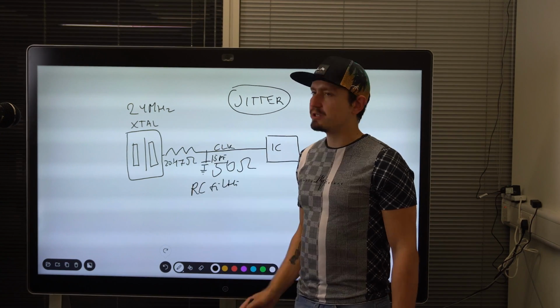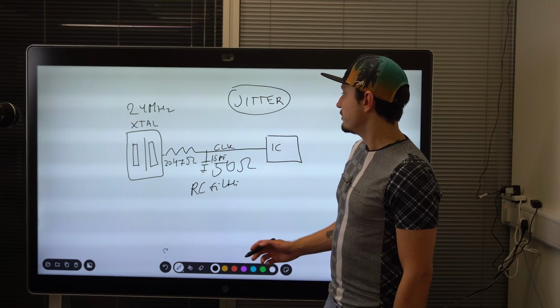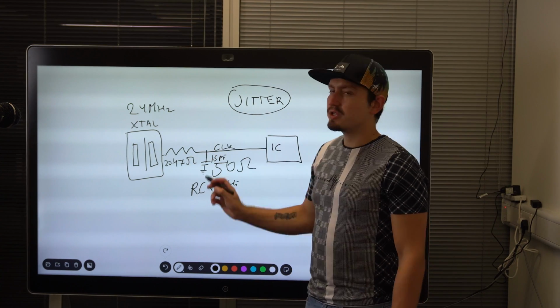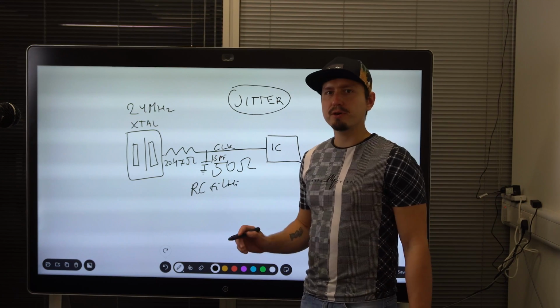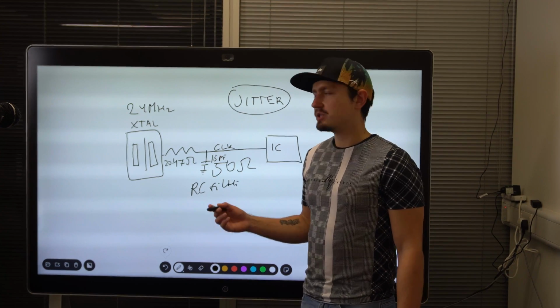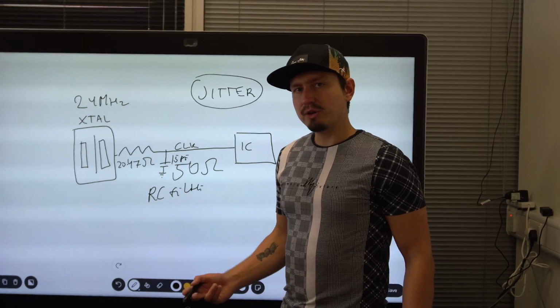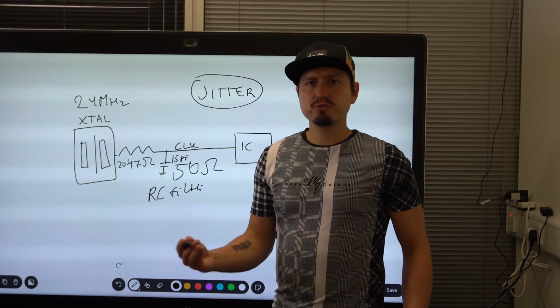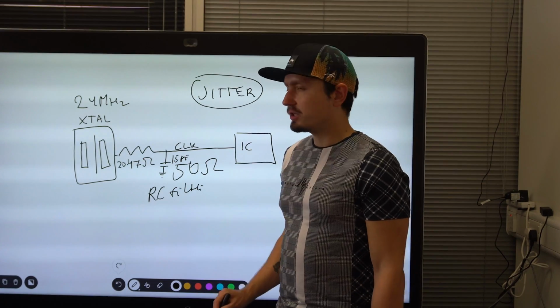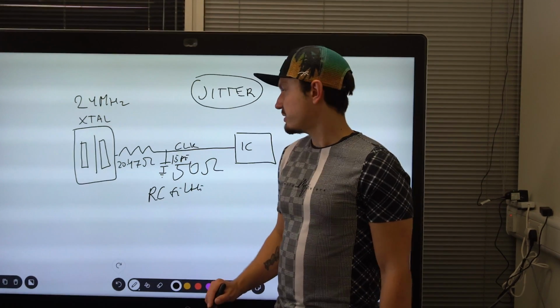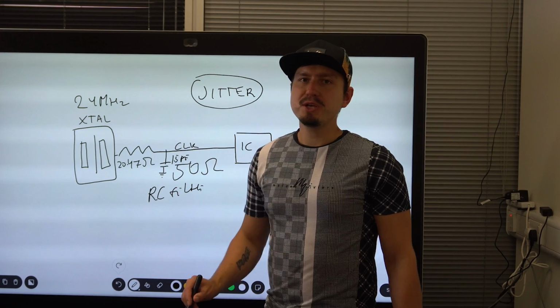failing at, let's say, 24 MHz. So this kind of narrows it down to this trace, because this is your only 24 MHz signal in this system, let's say. What sort of things you can do to reduce this emission? So first of all, you can try increasing this resistance or increasing this capacitance.